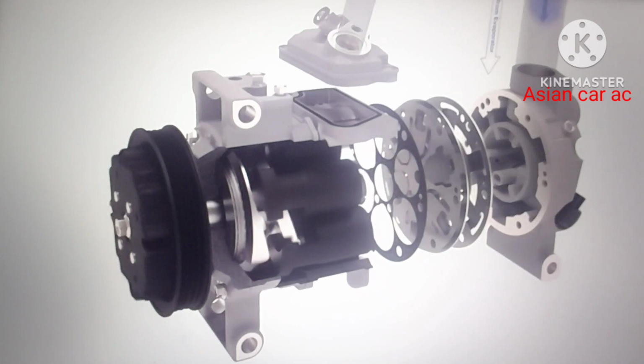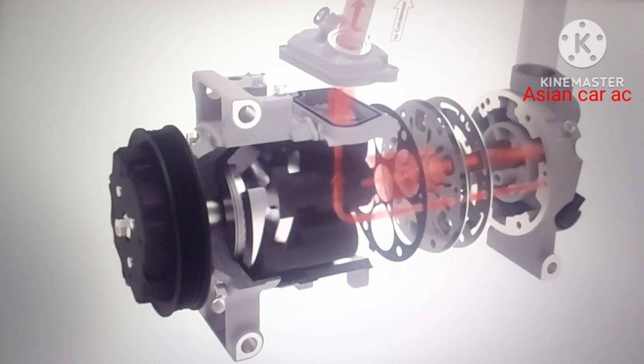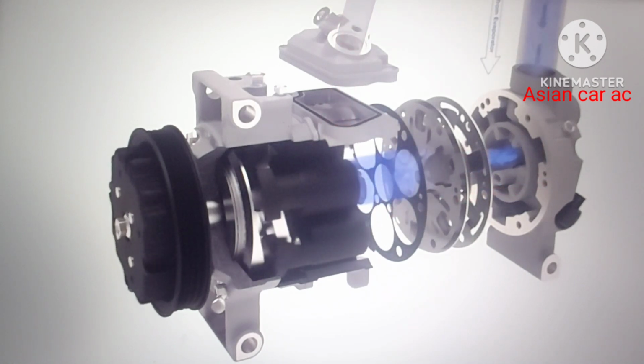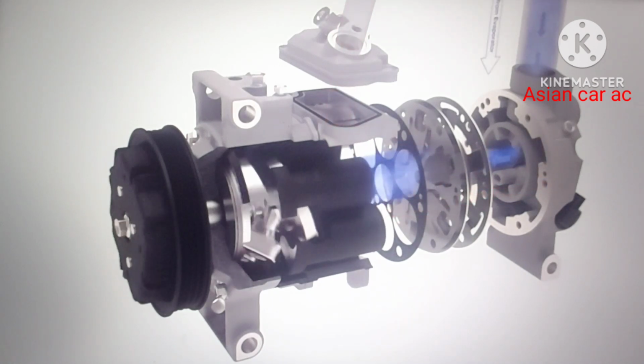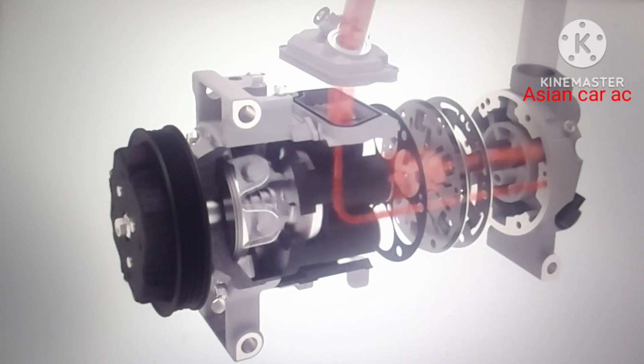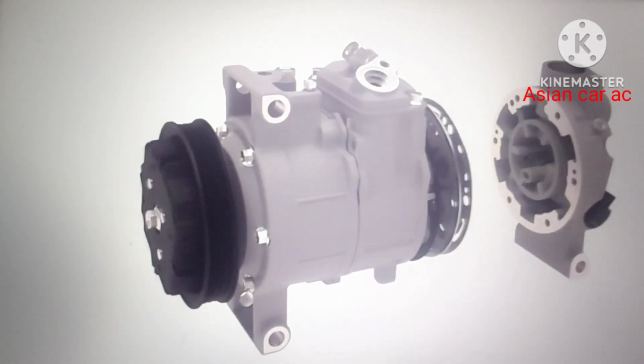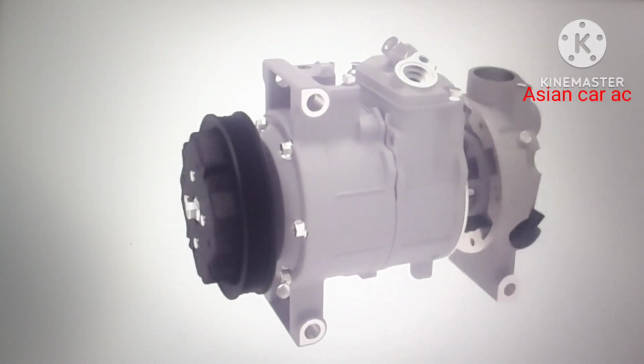The compressor sucks in the gaseous refrigerant from the evaporator, where this superheated refrigerant has absorbed heat from the passenger compartment. The gas is then compressed, which adds additional heat, and the high temperature, high pressure gas is then forced from the compressor discharge port to the condenser.